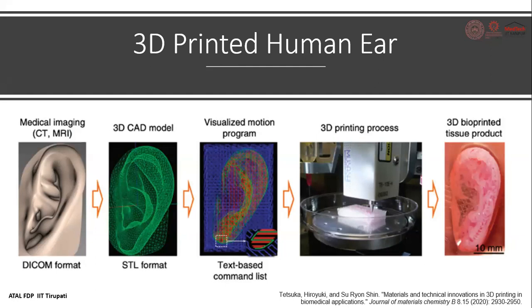Whatever data is collected is called point cloud data. With this point cloud data, we converted it into a surface, and that surface we tessellated. Why do we tessellate? Because tessellation tells where the material is placed and how it is placed, and where there is no material. All these things can be done by tessellation, which is STL. Tessellation means converting the surface into small facets. All these facets have a normal. With this normal, you can see where the material is present or not.